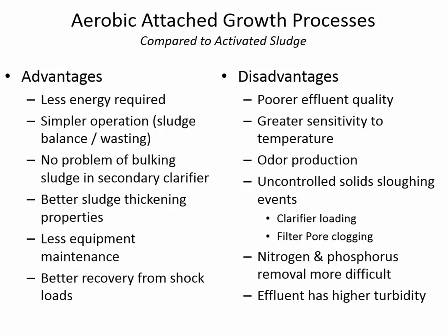Water holds on to heat longer than air does, and so overnight when it gets cool and that cold air is blowing over the filter media in attached growth, then that'll slow down the rate of removal even on a daily basis, and then of course through the seasons as well as it starts to cool off.